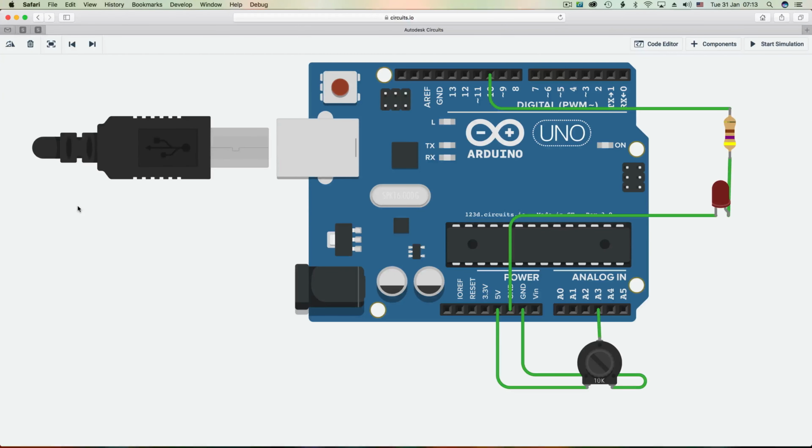Now, over in the circuit view, I will show you how to use a potentiometer wired up to an Arduino to generate an analog input, and how to wire up your LED to pin 10 instead of pin 8. So, to begin, your LED will require the 470 ohm resistor we have used previously. The shorter pin still connects to ground, and the resistor connects to the LED's anode pin, positive pin to pin 10. That's a very simple circuit.